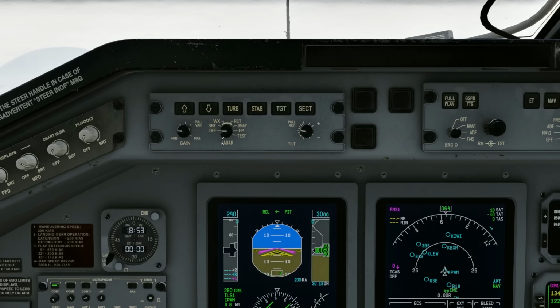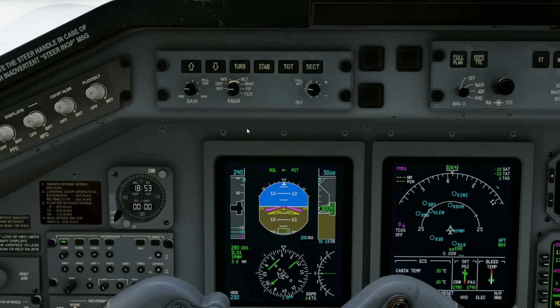The radar control mode, this is how we control the radar, so what mode we want to be in. Off, the radar is completely de-energized. Standby brings it to life, it's in a standby mode. And then weather is our default weather radar mode. There's a mode called React, and this is useful for looking for holes, the sucker holes, where a thunderstorm is so big that it actually absorbs radar returns as opposed to spitting them back, and it starts to make things look like a sucker hole when actually it's weather that's so big it's absorbing. Ground map is kind of the poor man's terrain radar. It's essentially a mode designed and calibrated to return the ground.